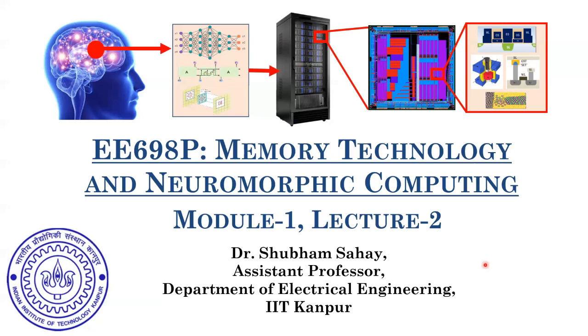Okay, so for this off-chip memory or DRAM, we saw that its memory capacity is quite huge. Its memory capacity goes to some gigabytes. However, its speed is slow. Also, its physical size is smaller, because typically DRAM consists of one transistor along with one capacitor. So its size is basically the size of one transistor, because capacitors are in general integrated on top of these transistors. So in terms of lateral area, it's not considered.